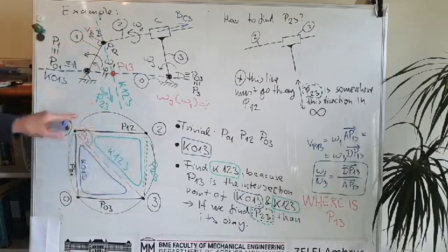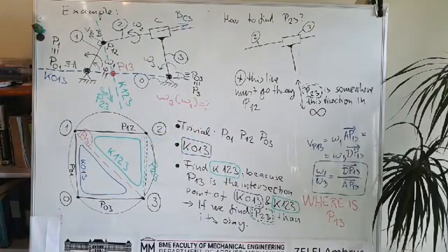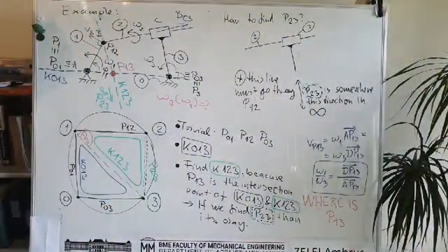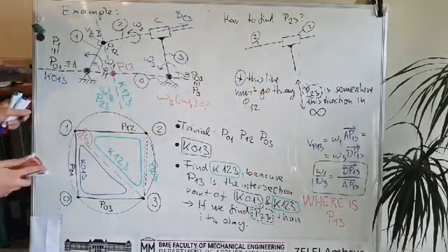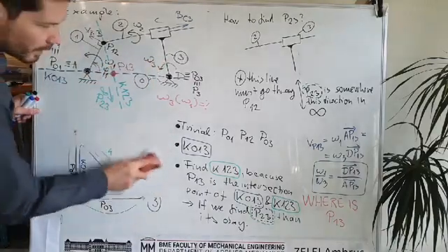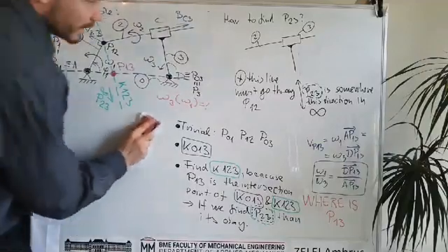Okay, so this is how to use this circle. And of course we use a lot of other things, but finally we could find this instantaneous center of velocity, and then we perform this calculation what was there. So now we are able to calculate the ratio of the angular velocities.